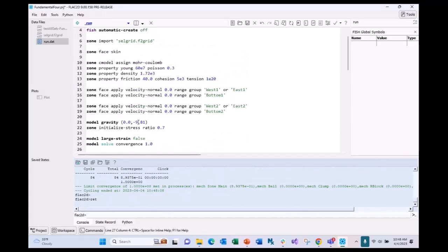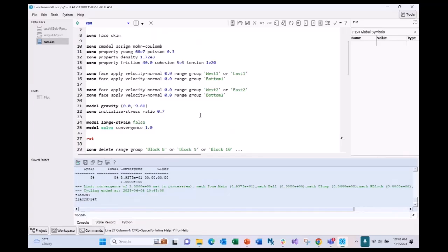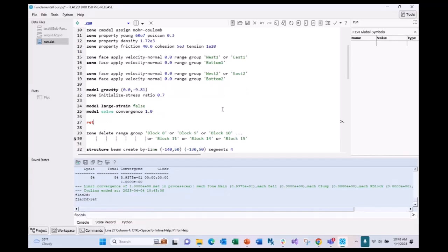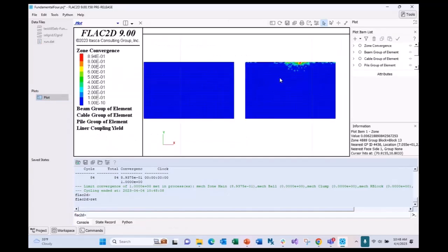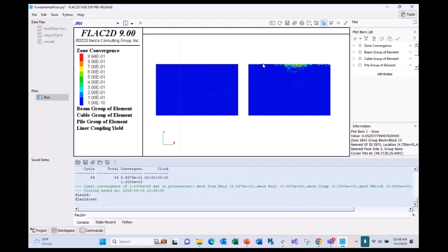Okay, I definitely, when I first went through it, I must have missed a couple lines. My guess is I probably missed a boundary condition. So it does converge, which makes sense because that's how I had initially made this example. I have a feeling I just missed some lines. Anyway, going back to the end of the solve convergence, let's take a look. Remember convergence 1.0, so there shouldn't be anything greater than 1.0 in this plot. Okay, so it's converged.